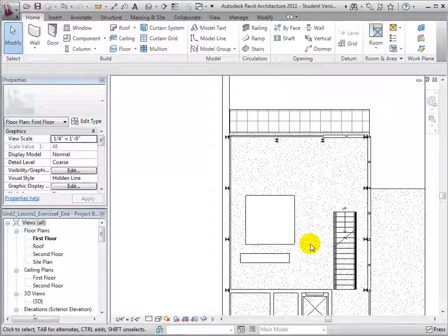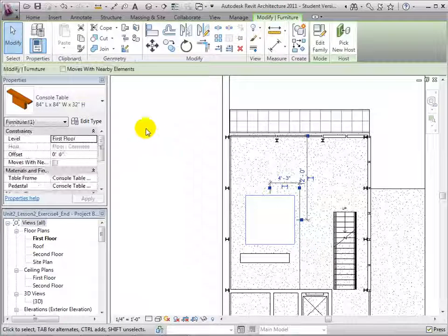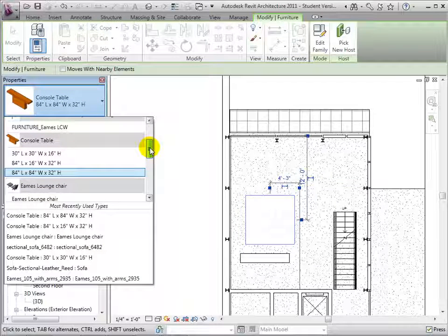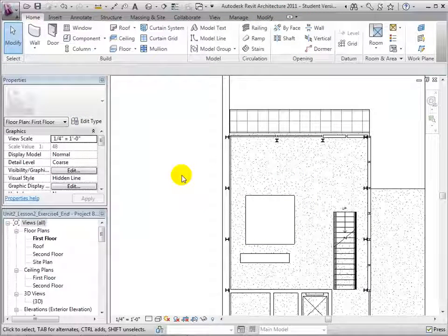We can also share our Revit family file with others. Anyone can use the Load Family tool to load the component family into a project, then create new types as needed and adjust the type properties to set the dimensions for each type. They can also set the materials for each of the forms, the tabletop and the pedestal, as instance properties for each instance placed in the project.